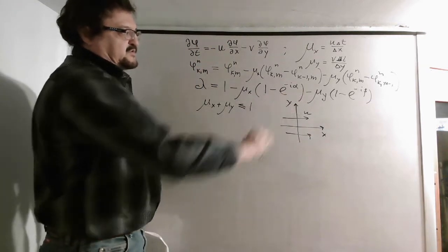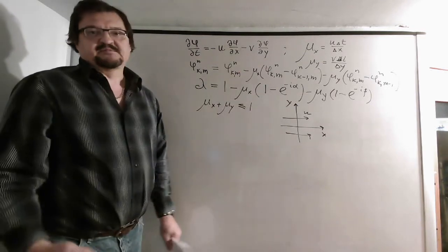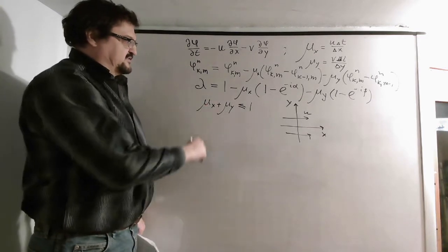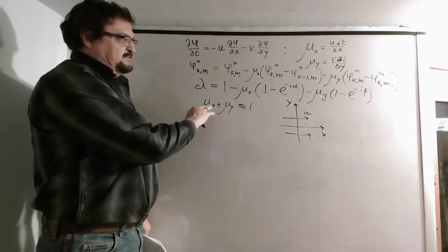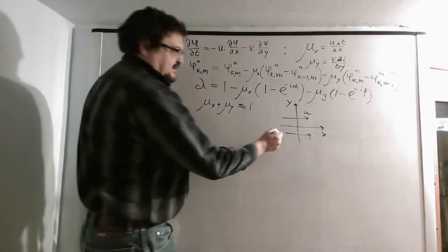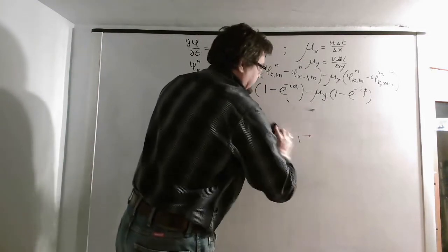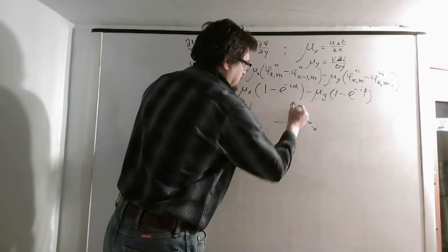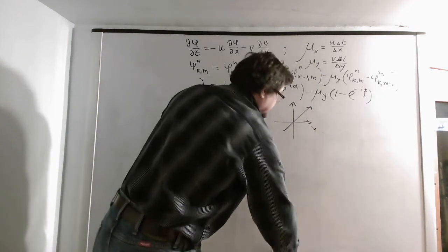Of course, then there is no flow in the y direction, and the scheme becomes effectively one-dimensional, and then you have the stability criterion that mu x should be smaller than 1. So you see, the only difference appears when you have diagonal flow like that. If you have a flow like that, this is your c vector, the velocity vector.